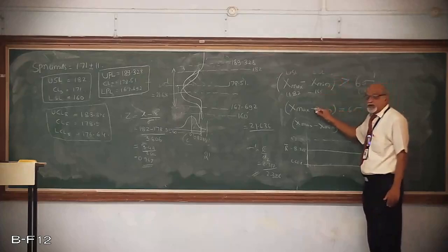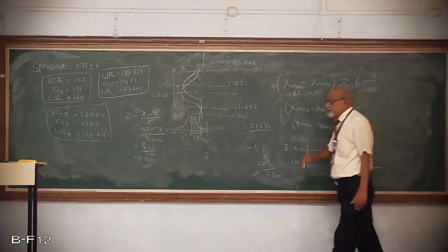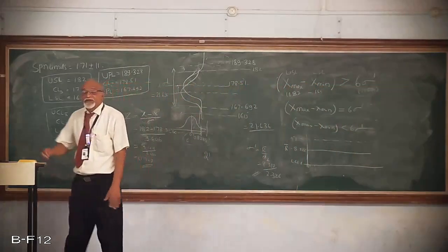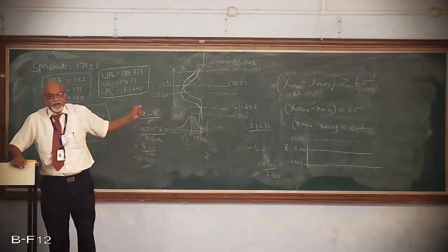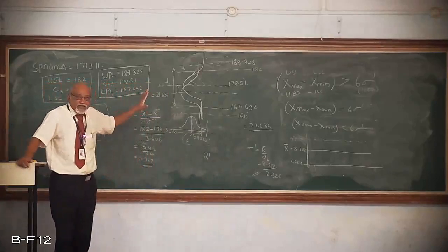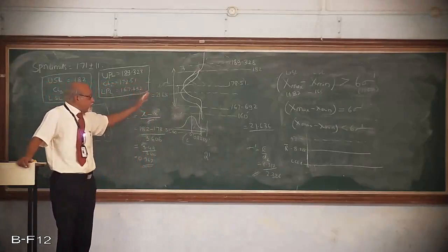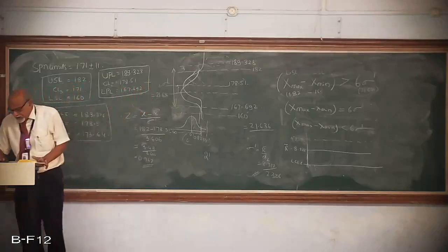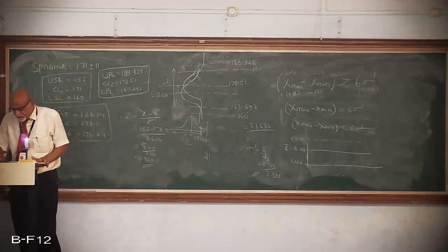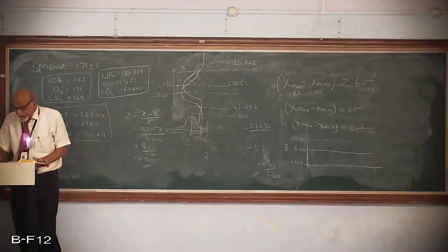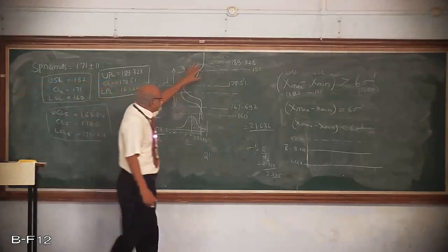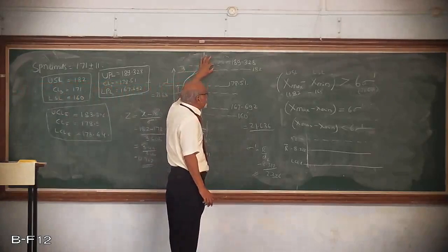Okay, this is how we can compare the process capability. This is nothing but the analysis of process capability. Through this example, I am trying to tell you about that. Now coming back to this example and answering that question, the C part: to what value the process average can be shifted by relatively simple machine adjustment, what would you suggest as the aimed-at value for process centering in the immediate future? Because now 18% defective items are there and rework is being carried out.